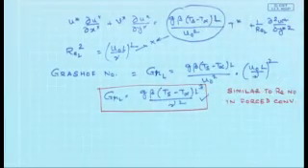So, any relation that you would get for natural convection should contain the Nusselt number as a function of Reynolds number, Prandtl number, and Grashof number. So, unlike forced convection, we will have an additional term present in any correlation of natural convection, which is the Grashof number. Let us look at the Grashof number in a bit more detail.